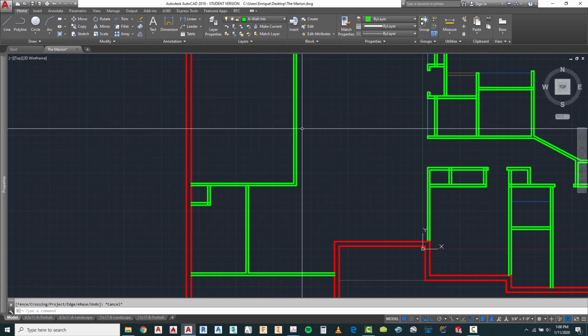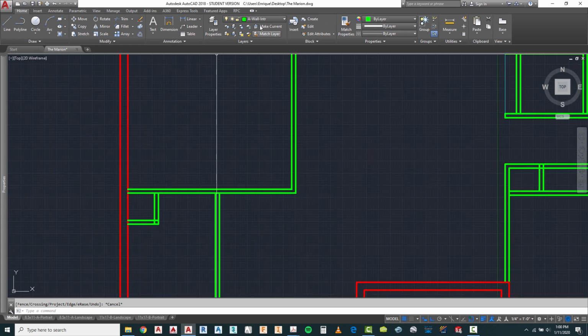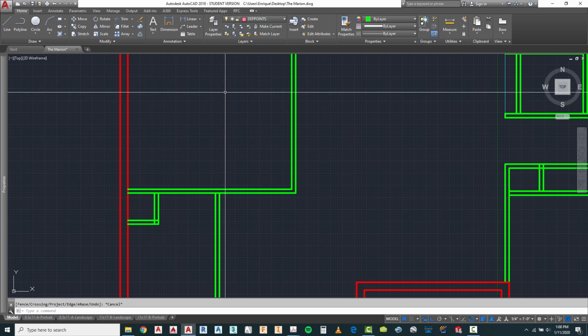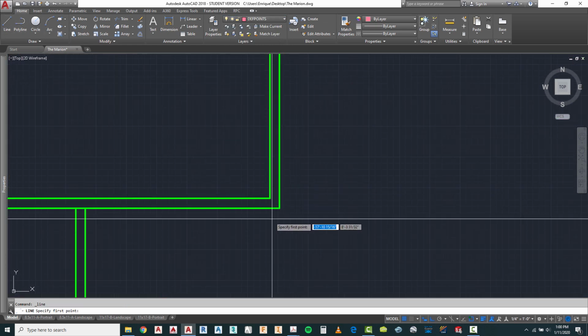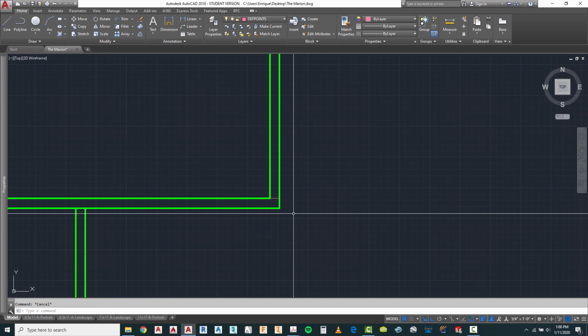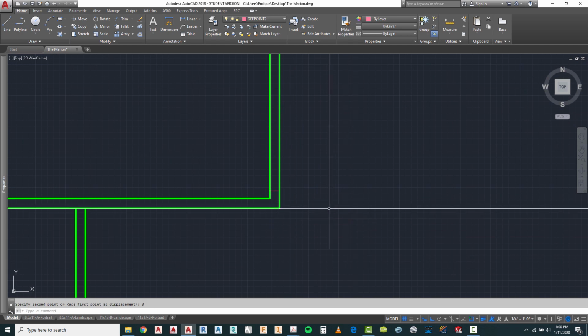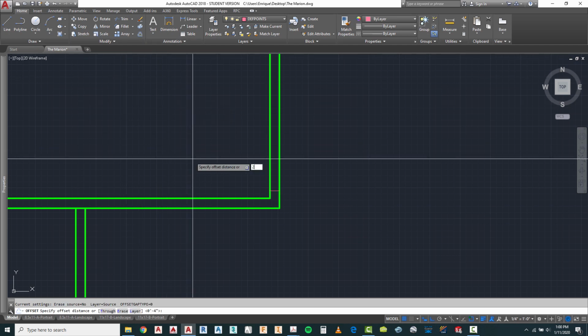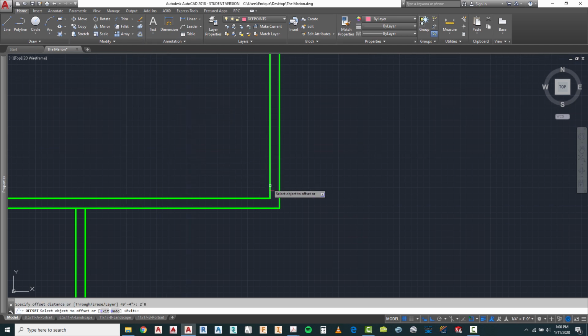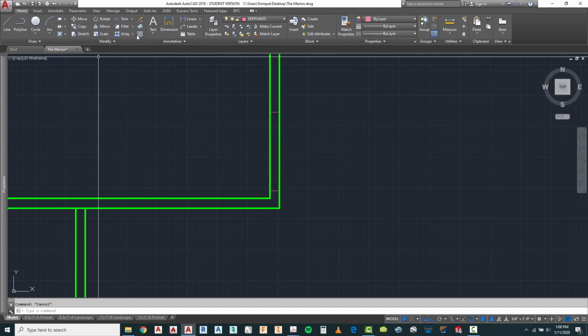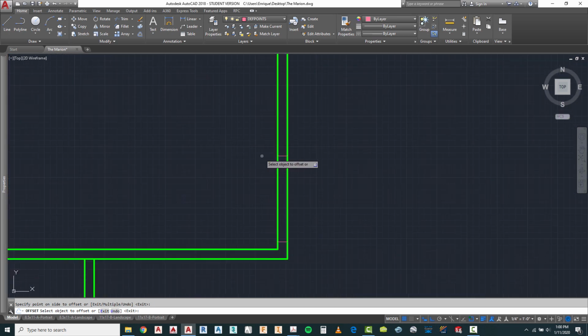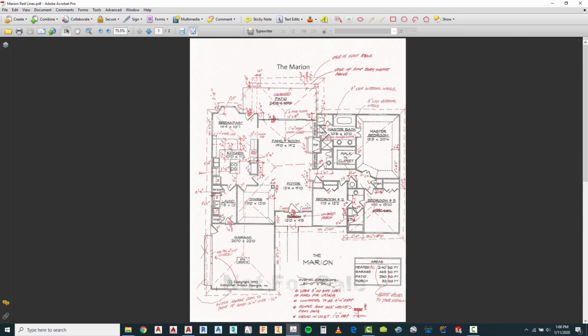Let's try this pantry closet in here. I'm going to go back to the A to the depth points, and I'm going to draw a line here. I can move it over my 3 inches. I'm going to offset it 2'8". That is the size of the door that's got to go in there. I'm going to offset the 3 inches again. And I'm going to offset this 2 foot 4 inches deep. And that is to the outside of the wall.